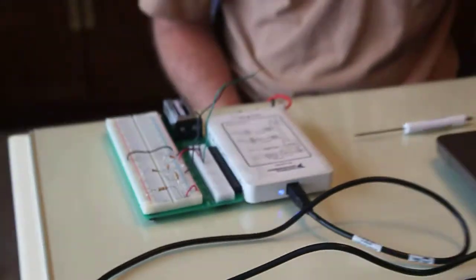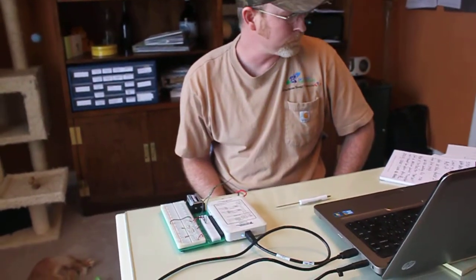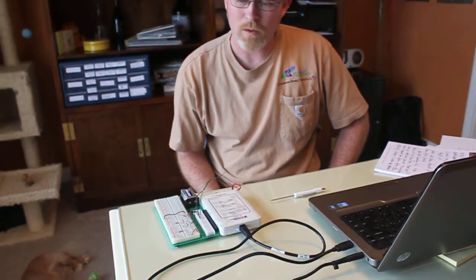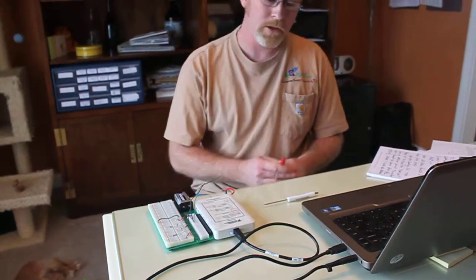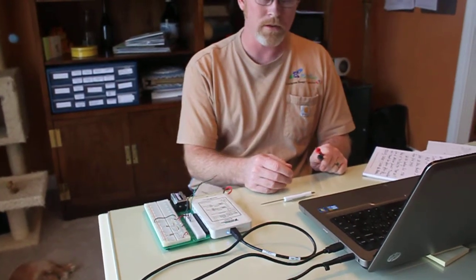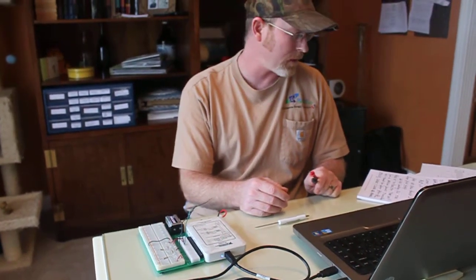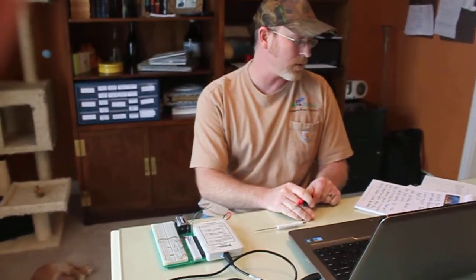Or vice versa. You can take the current and use the equation R times I squared, and that will give you your power. And what you're wanting to do is see which value of your load resistance meets your maximum power transfer theory. And you need to know the power dissipated from each of the 10 resistors that you choose to do this.